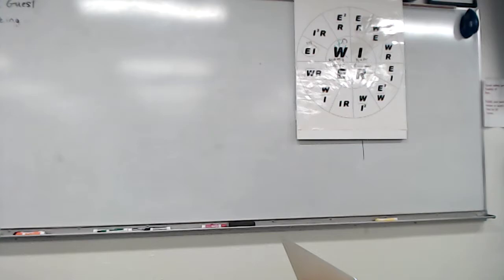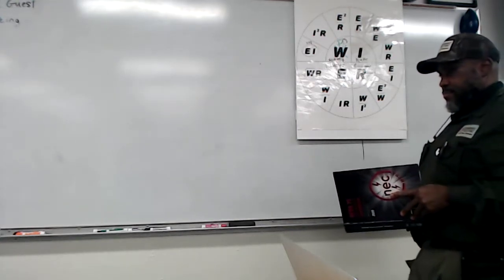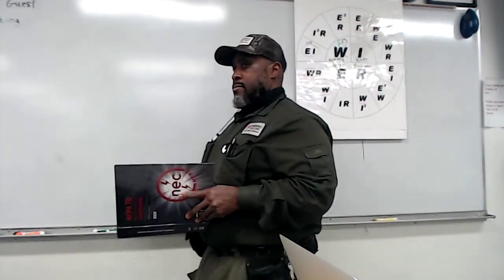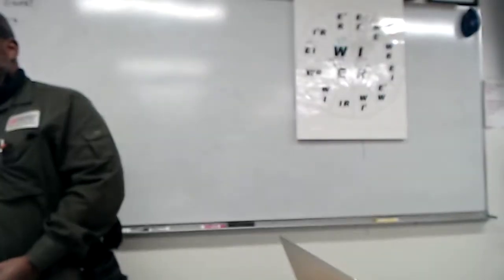You said 3. So you need to look at your code book. Do you know how to navigate your code book? I need you to go to 314.16 B1, conductor fill. It starts out with conductor fill. Mr. Jarman, a highlighter.